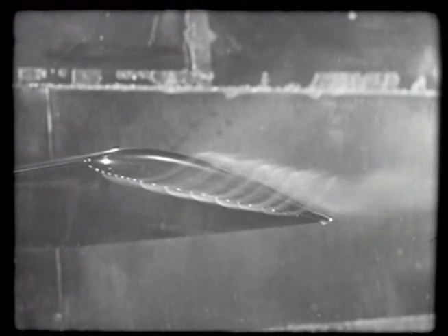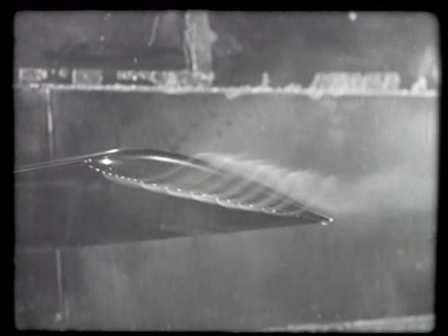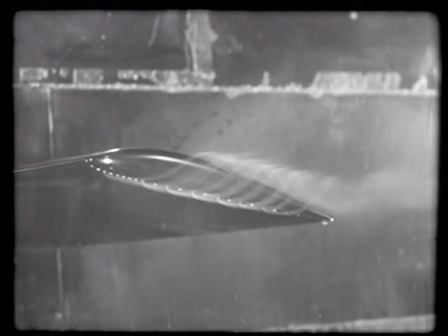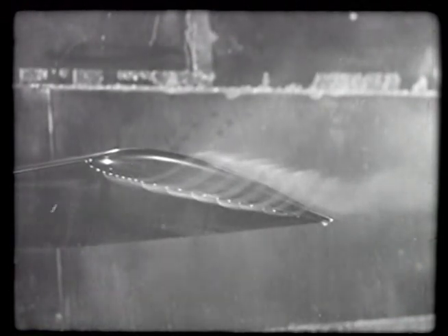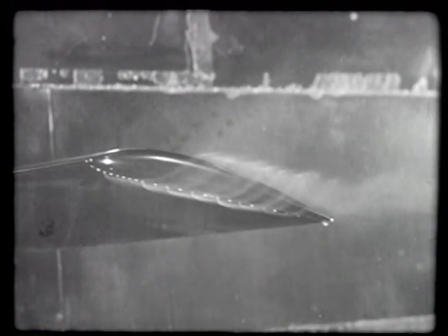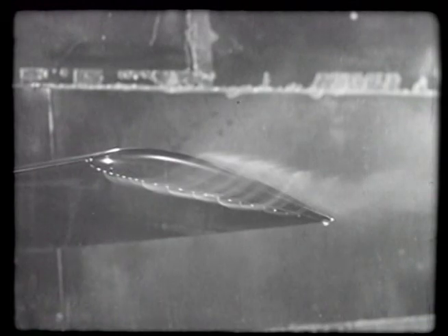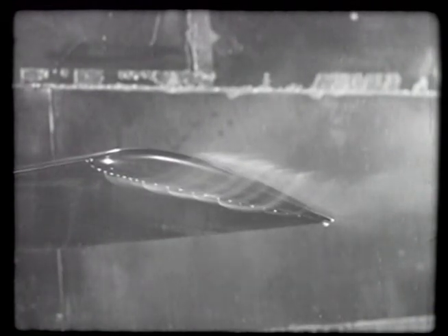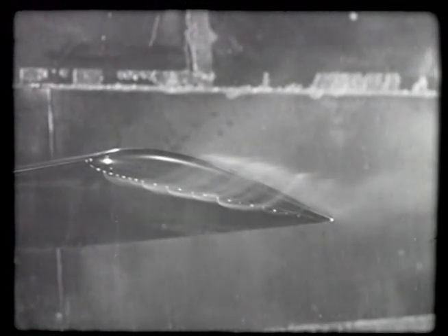Again, a picture from the side view where we see the single flow line, and we observe one thing, that the slope of the line increases towards the rear, because this rotation is caused by the lift. Now, the front part has not all the lift, but until you get to the rear end, you have assembled all the pressure differential which is there, and therefore the spiral gets steeper and steeper towards the rear.